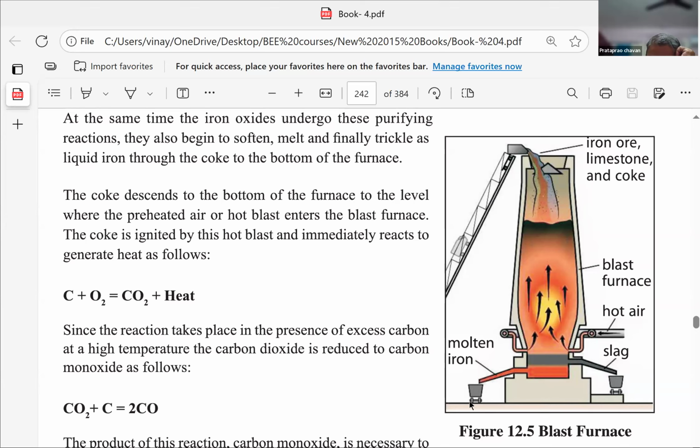So when you are carrying it through the trolleys, they are to be heavily insulated so that the metal inside does not lose heat and solidify. It should not be solidified, otherwise it will not flow into the mold and will not go through all the nooks and corners of that mold to form a correct size of product.